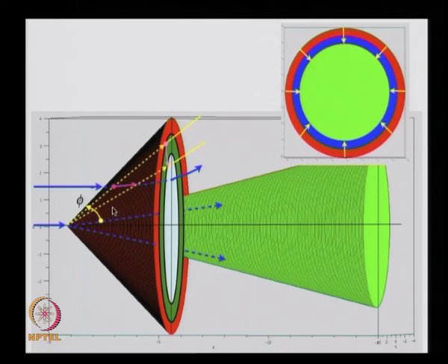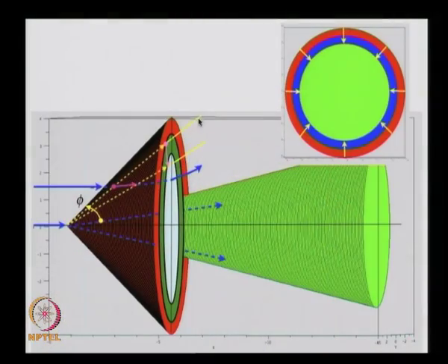And if you remember, about the vertex I have a symmetric flow happening. From what we did regarding the conical flow, there was not any change in the phi direction as far as the flow is concerned. Therefore, there were no changes in properties in the phi direction. And properties were constant along the radius, along the radial line. Properties are constant over it, and they vary only in the theta plane. So, if I change theta this way, in this plane it will change. Therefore, the only dependent variable out here is theta.